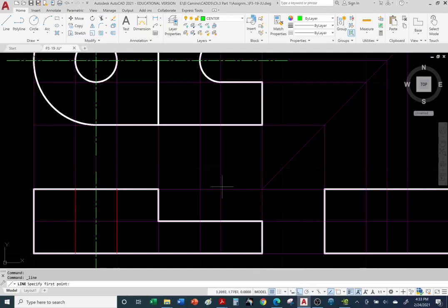If I'm going to create the center line, you have to make sure it lines up with the top view. Everything has to line up. So I'm going to turn object snap back on. Now when I use the line command, see how it snaps? The green X is intersection. A circle is center point. A square is an endpoint.